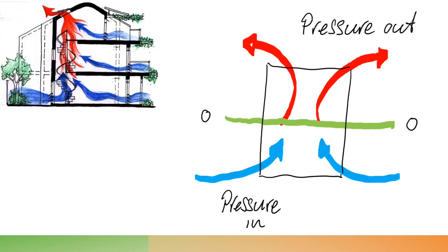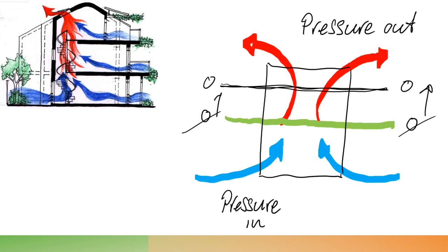What we don't want is our pressure balance point shifted. Let's say that was 0 there and 0 there. We've just shifted this line upwards, up to there. So generally the building is out of balance, and the majority of the building is going to be cool, and then your attic's going to be lovely and warm. So you can either move into your attic with a sleeping bag, or you can get this right and make sure that the building has a proper stack effect.